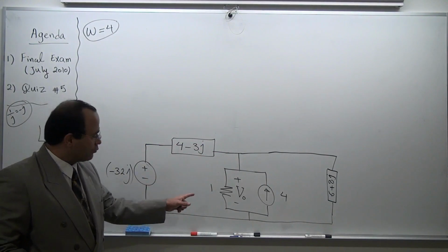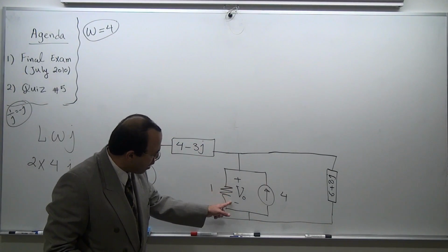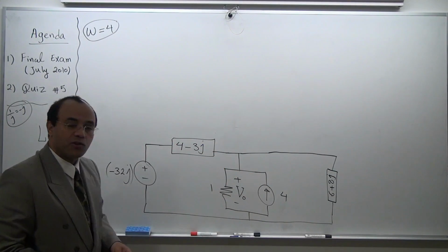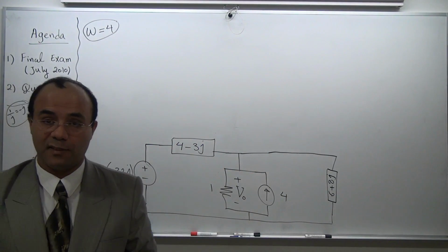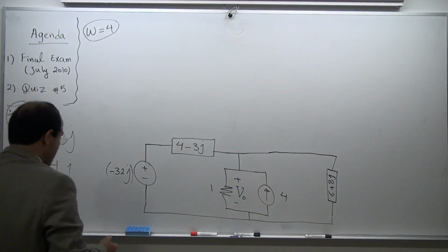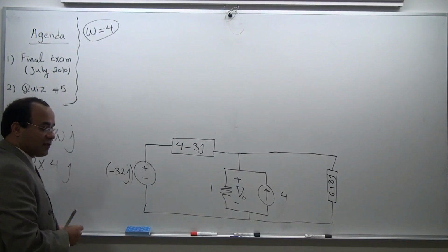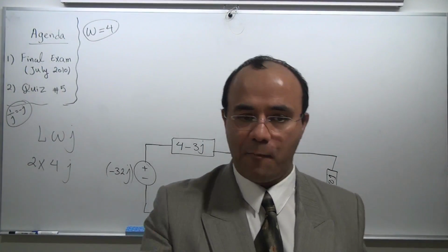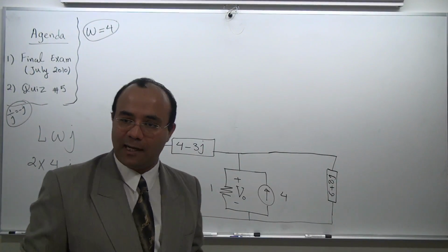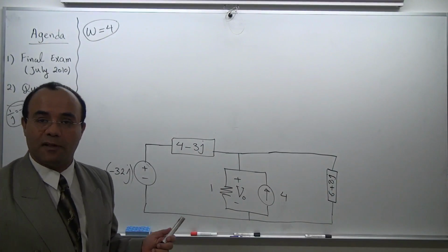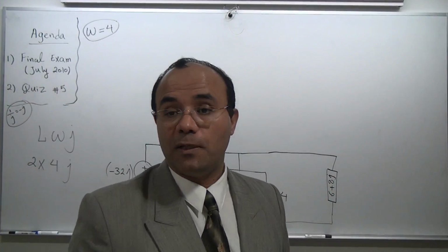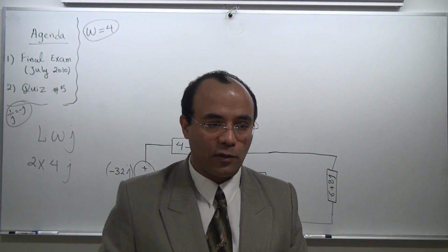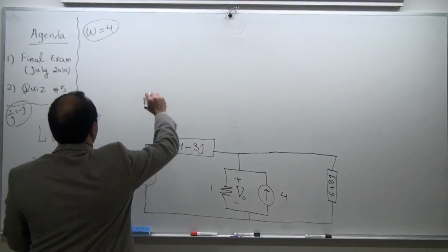Whatever technique I'm going to apply, I have an eye on this 1 ohm and the voltage across it, and I have a bunch of complex resistors in my design. Let's begin. I want to do superposition. Superposition says take a look at the number of excitation inputs and grab one at a time and shut down everything else to 0. If it is a voltage source, when you shut it down to 0, that's going to be a short line. If it is a current source, when you shut it down to 0, that's going to be an open line. So let's do this one at a time.